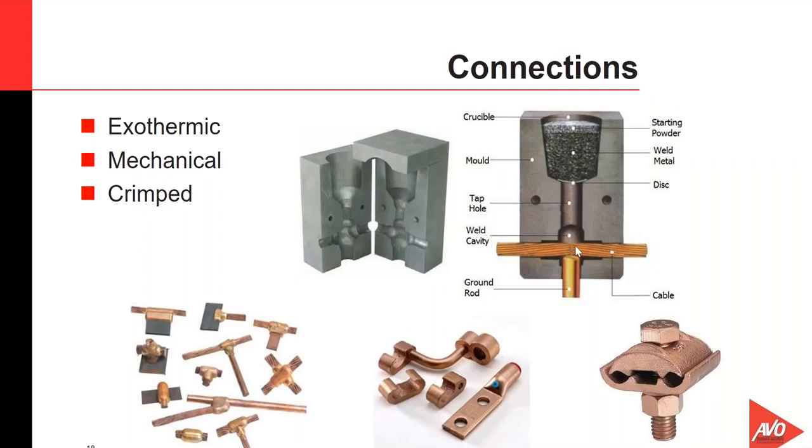Of course, with this welding process, you want to make sure that once it's done, you let it cool, and when it's done cooling, clean it off. There will be some slag on top of the exothermic weld. Just hit it with a metal hammer to break that slag off a little bit, then hit it with a wire brush and coat it with a grease.